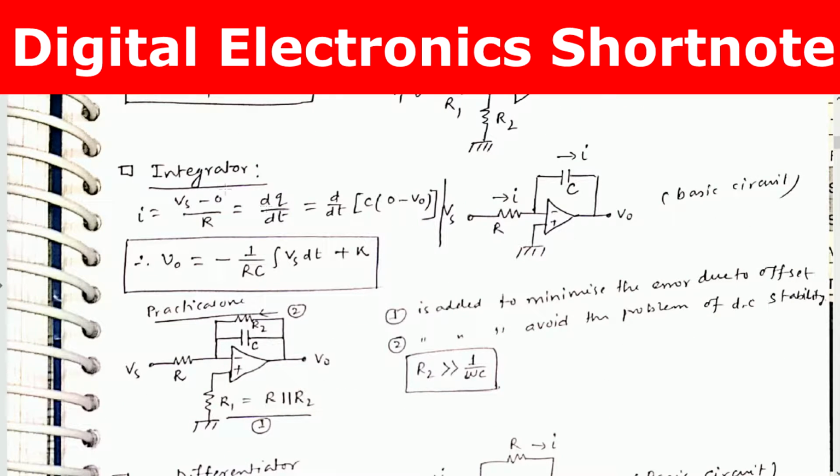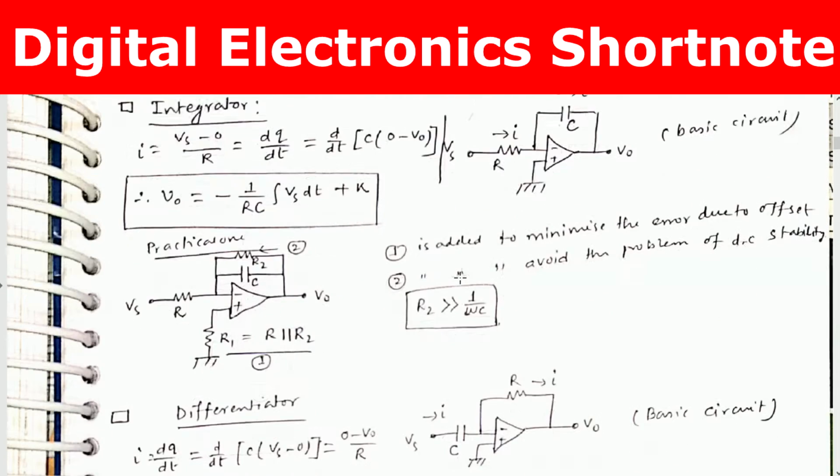Integrator circuit. Remember for an integrator circuit the capacitance lies in parallel here as the feedback impedance. So I equals Vs minus 0 by R equals 0 minus V0 by this impedance, and this current I equals dq by dt, and q equals C v, C into the voltage difference 0 minus V0. We got the output formula for the output voltage V0 equals minus 1 by RC integration of Vs dt plus a constant.